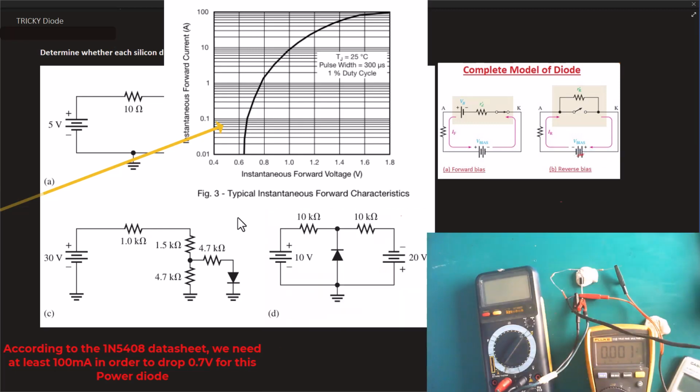Okay guys, we are now on the last case here. Now we also say that this particular diode is forward biased. Upon doing the mathematics of this case, we found out that there was a negative 5 volt here, because each one of these resistors had a 15 volt across it, and the minus 20 volt here was then summing up, subtracting and giving us a negative 5 volt. Now because the cathode was at negative 5 volt, that means the anode was more positive and this diode was forward bias. Now let me turn on the power supplies here.